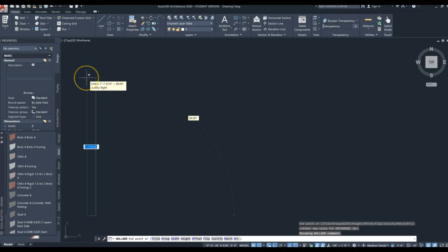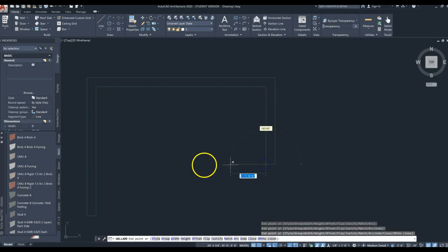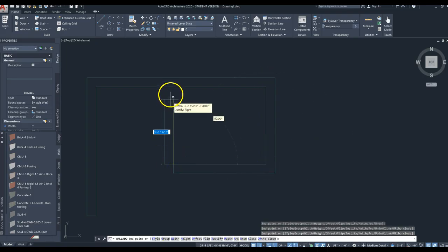Okay, first let's just go ahead and draw our first wall. It doesn't matter how long it is, but choose an endpoint and click your mouse again. And then, hey, it's already creating the next wall for you. Alrighty, so then you can just continue on, click your mouse again, click your mouse again, and it's really easy to build walls in this fashion. If I go to the end of this run, it's going to snap in with the existing wall. So let me just drop my end point right here, kind of in the middle, and look at that. It snaps together.